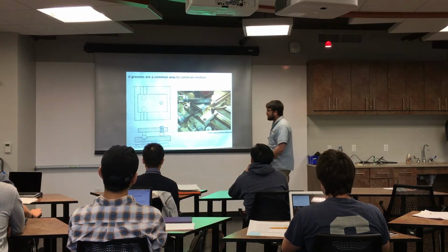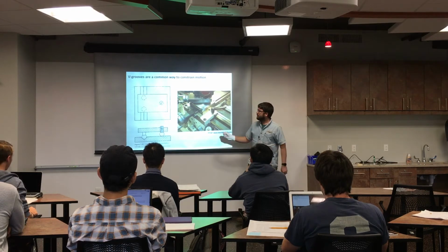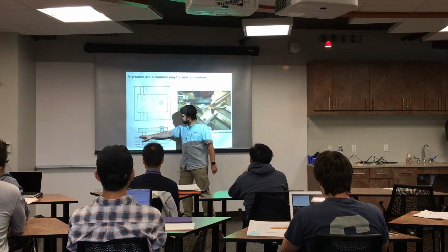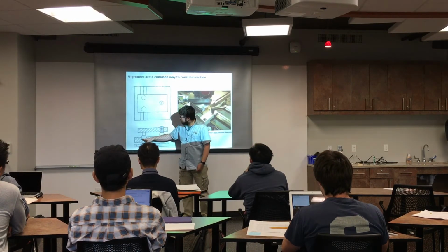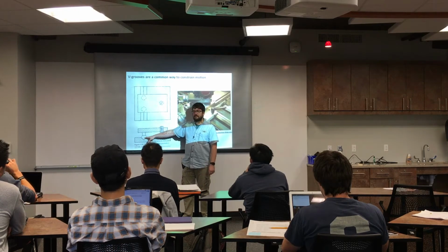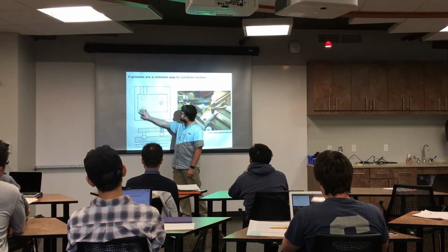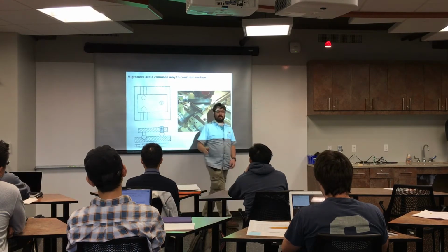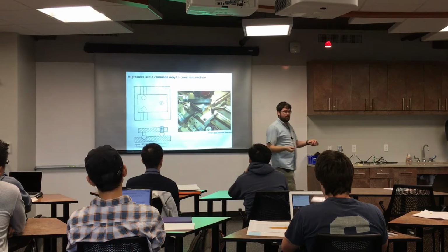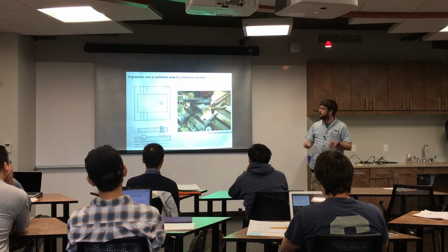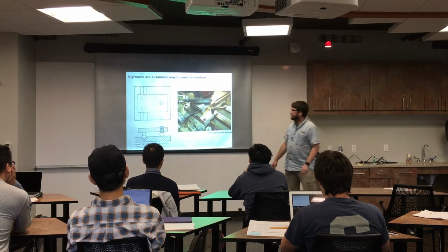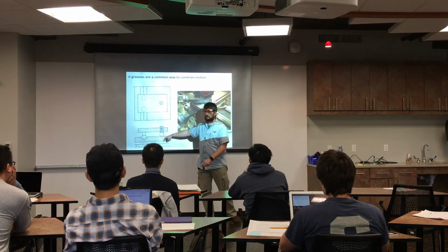One way that you can do this, and this is called kinematic design, would be, let's say we've got a V-groove in a piece of metal, and we put a ball bearing here on the bottom of this plate. So we're constraining this plate, top view and side view, to move only in this direction, only one dimension of motion. It can't twist, and you could lift it, but you probably wouldn't want to, right? And then this is just a support out here.